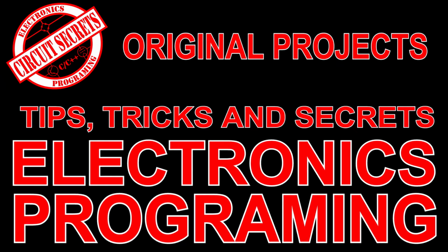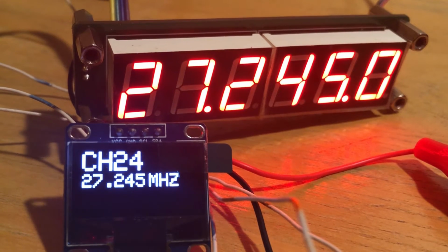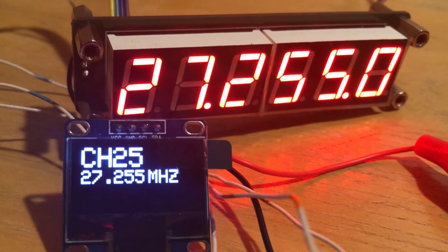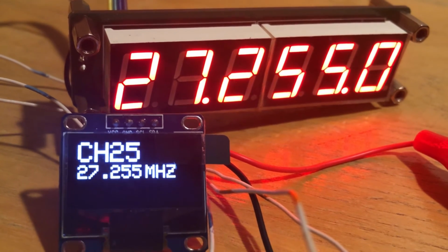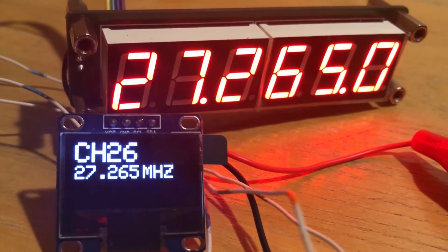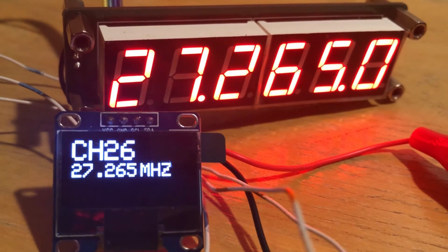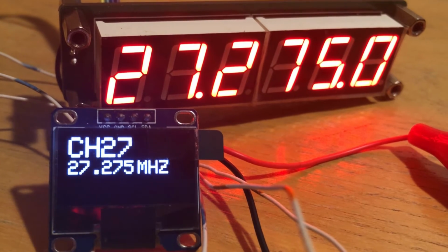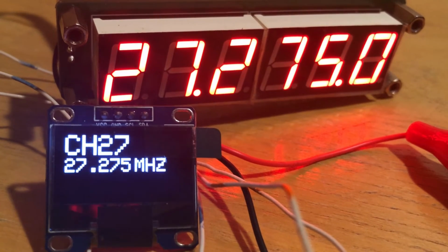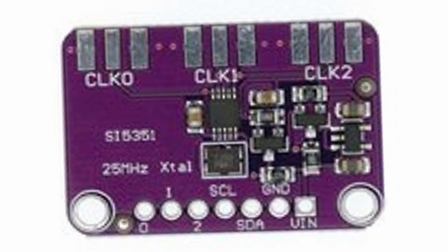This is our next stop on our way to creating a VFO to convert a 6-channel CB radio into a 40-channel. The si5351 is a clock generator that has a frequency range of around 8 kHz to 160 MHz. This makes it the perfect component for building signal generators and VFOs. A VFO is a variable frequency oscillator. The si5351 can be used as a direct replacement for crystal oscillators. A crystal oscillator is a fixed oscillator that generates a fixed frequency signal.